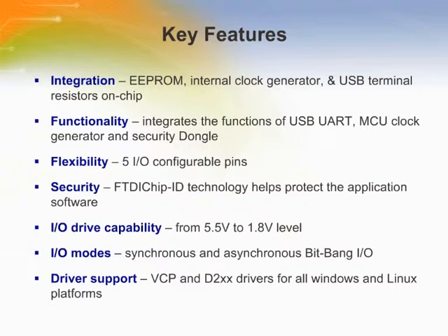The FT232R includes onboard EEPROM as well as a master clock generator, 3.3-volt LDO regulator, reset generator, and USB termination resistors. The fully integrated EEPROM allows configuration of the control bus functionality, signal inversion, and drive strength selection. There are 5 configurable CBUS I/O pins to be configured as sleep, transmit enable, power enable, MCU clock output, LED drive, or GPIO pin. The FT232R also includes the